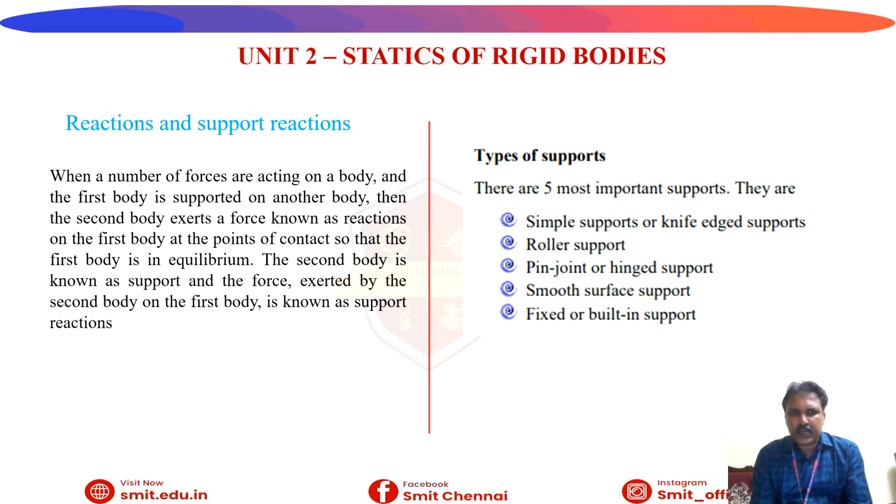This slide represents the reactions and the support reactions. As I already told, whenever there is a point of contact, we'll have a reaction support, one force that will be acting in a perpendicular direction, that we already discussed in the last video, that is part 3 video of Unit 2. When a number of forces are acting on a body and the first body is supported on another body, then the second body exerts a force known as reaction on the first body at the point of contact so that the first body is in equilibrium.